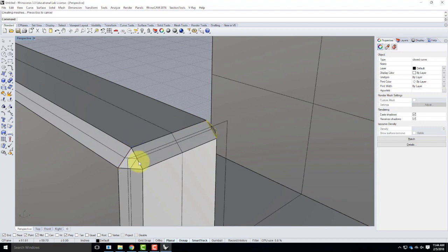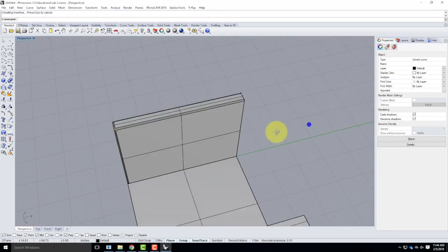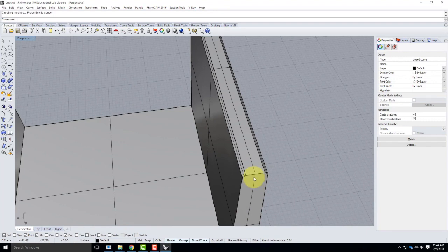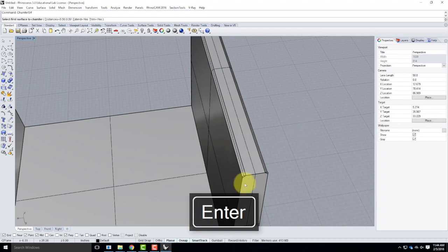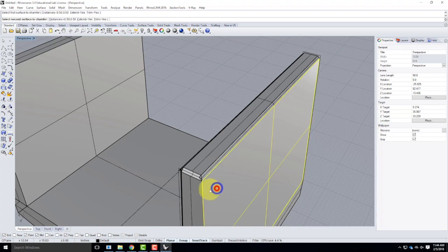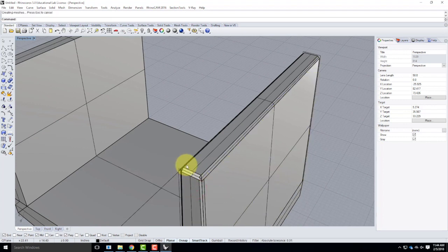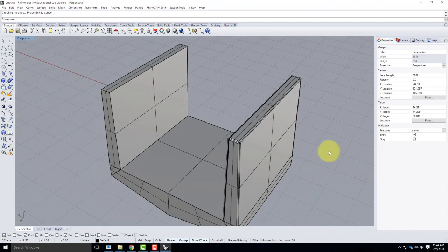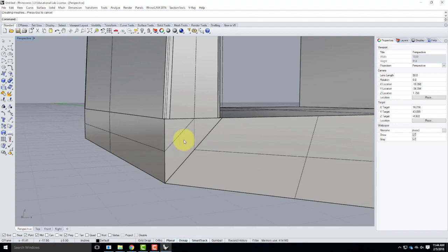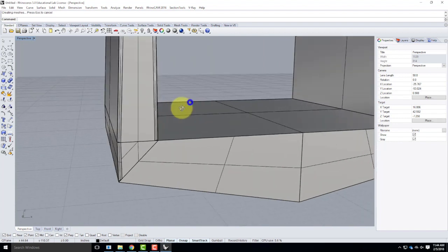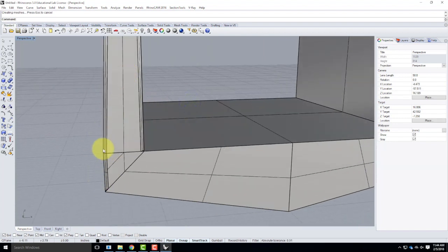So I've done these upper 2 corners. I obviously have to come over to this back side and finish my chamfers. So chamfer surface, there, there, there, and there, and there, and there. So I've got the same 2 little nasty corners to deal with. As I come down here, I need to do the chamfer surface from here to there, and you see that that lines up nicely. If I had done this in one big shape, it wouldn't seam as easily right there.